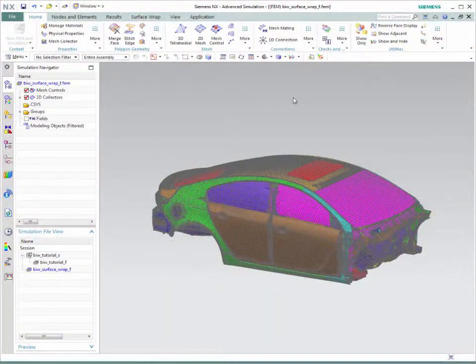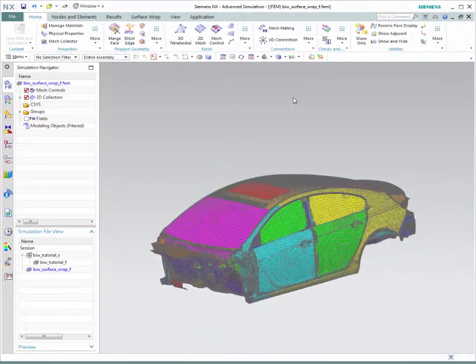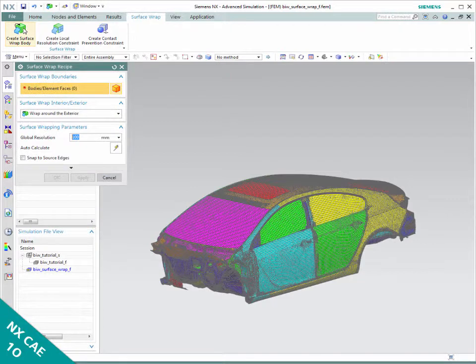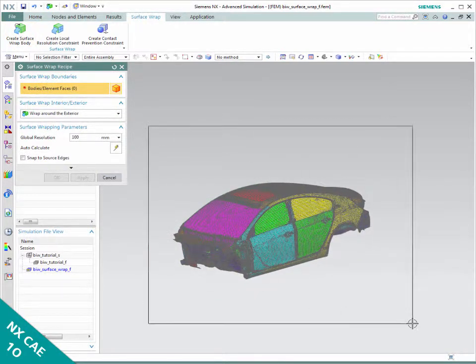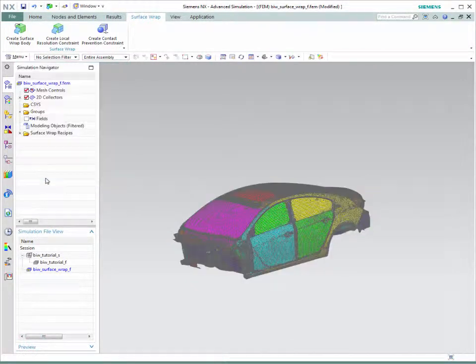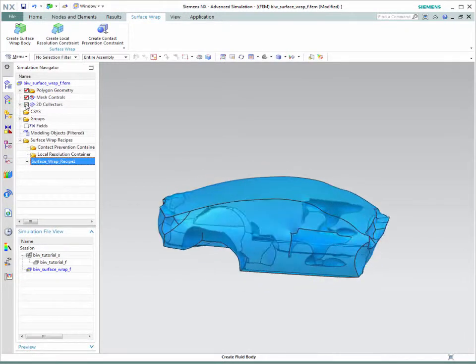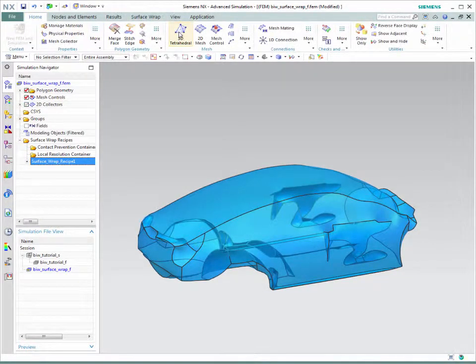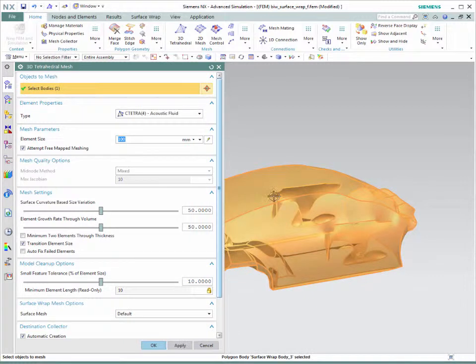Very often analysts don't have the underlying geometry, they just have a mesh-based representation. But now you can also take in meshes rather than just geometry. So that's a big step forward, because you need not have the underlying geometry, which is very often the case. And so you can just start off with, say, an orphan mesh with no underlying geometry, and you can create the internal fluidic cavity out of there, just as you would with regular geometries.